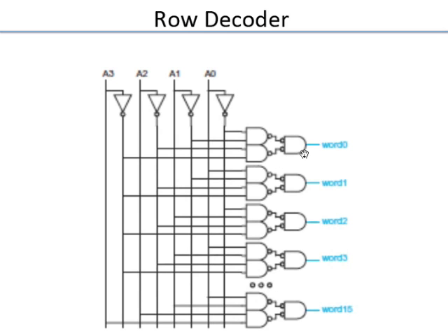This is a 4 input AND gate which has been implemented as a sequence of 2 input NAND gates. This is a NAND NOR structure. If you push the bubble on this side, it becomes a NOR. So this is really a NOR gate which is just written this way, so that it becomes easy to see that it's a 4 input AND function.